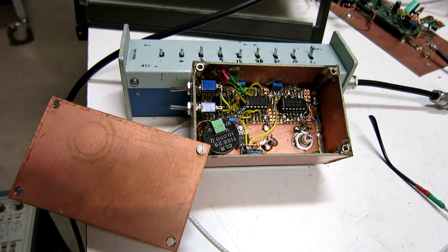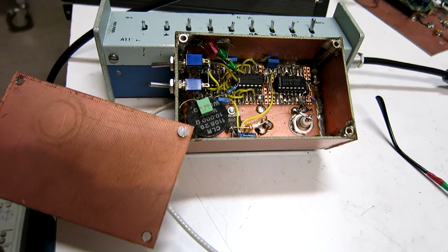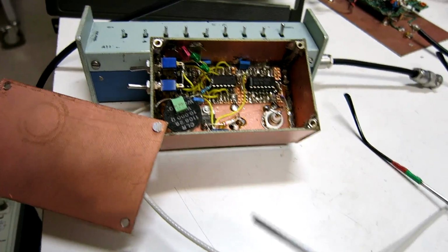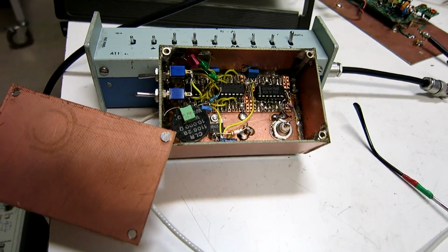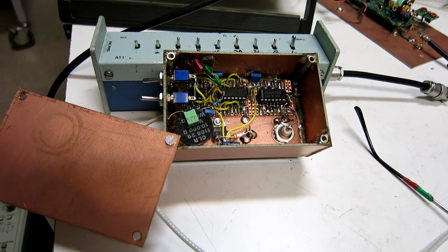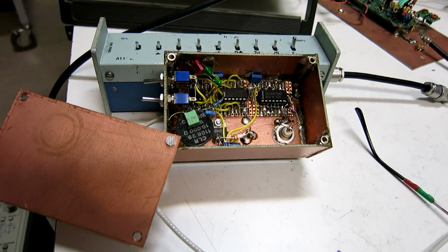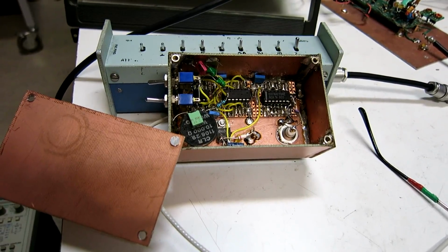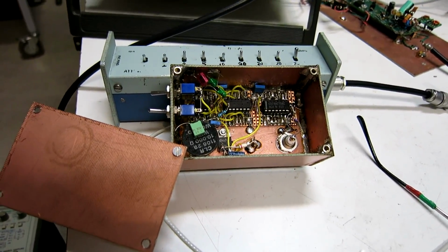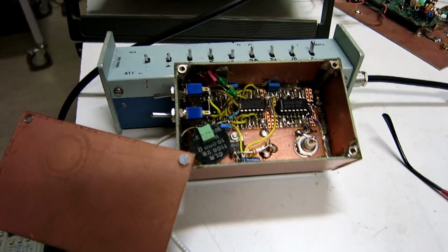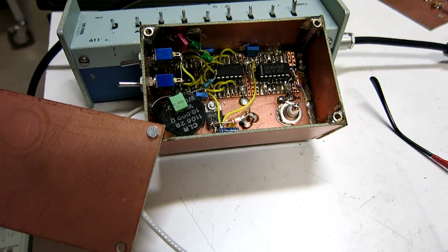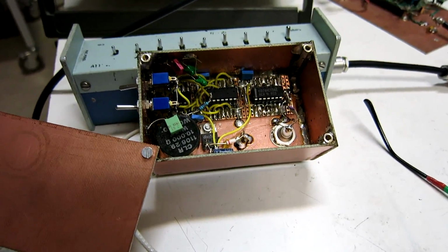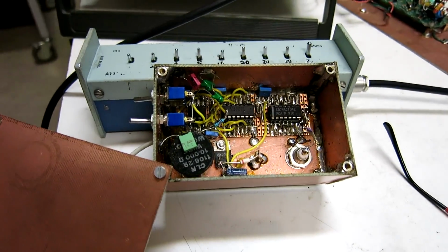This is the interior of the proper pulse generator. It has a 555 here. The switches and the potentiometer can set the frequency. It's followed by a frequency divider, 74AC74, to make sure we have a square wave with the same length of high and low. And then it's followed by a driver. In this case it's a 74ACT04. It could be a 74AC04, but I take what I have in the junk box.